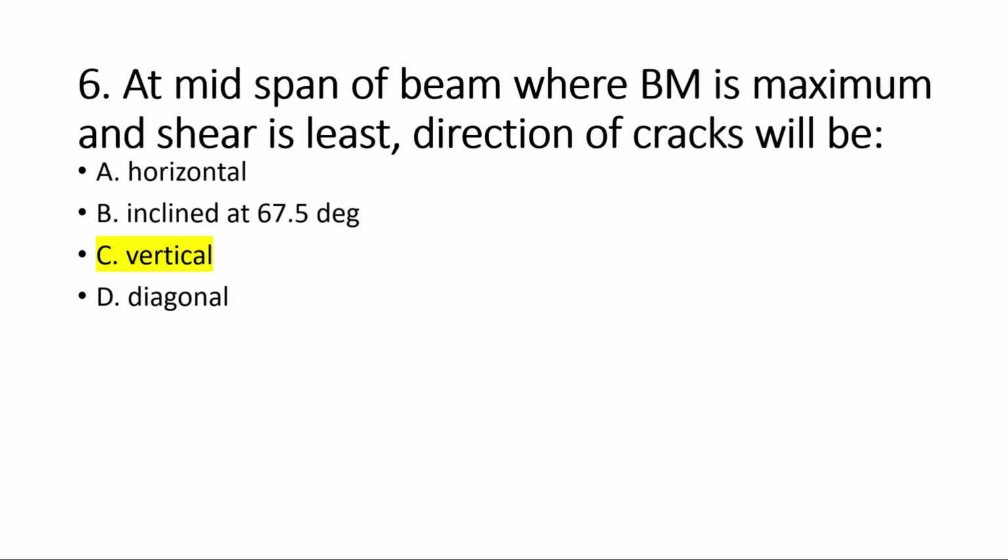At the mid span of a beam, where bending moment is maximum and shear is least, the direction of cracks will be, okay, the direction of cracks will be vertical. We know that at the mid span of the beam shear is generally negligible, or you can say zero, and due to principal flexural stresses the cracks are vertical here. So the cracks will be vertical, and here option C is correct. And move on to the next question.